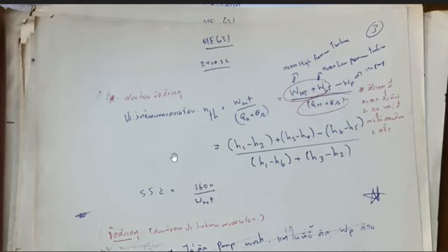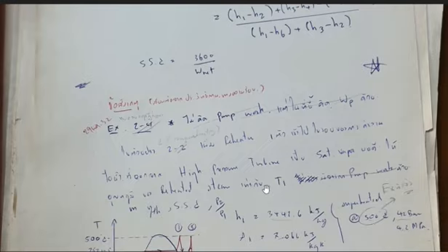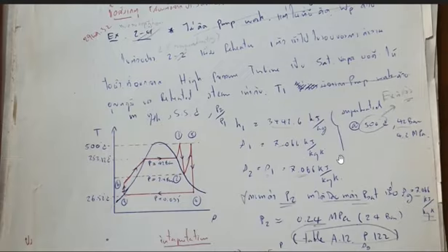And if we expand the formula in terms of entropy, we can get something like this. And the specific steam consumption again would be 3,600 divided by work net. And this is the example that we are going to use to demonstrate how to find all the needed values for the thermal power plant cycle.